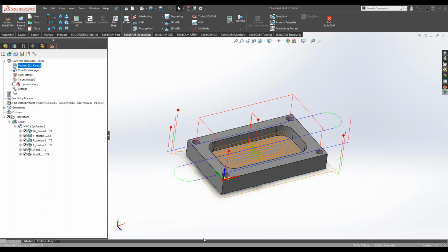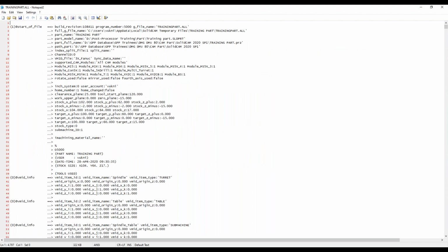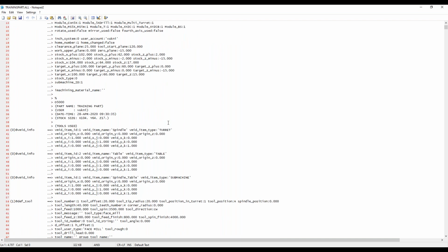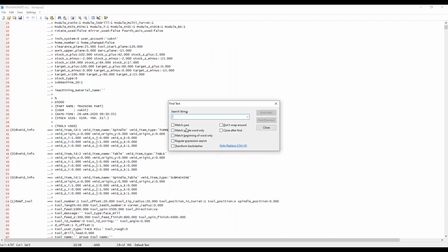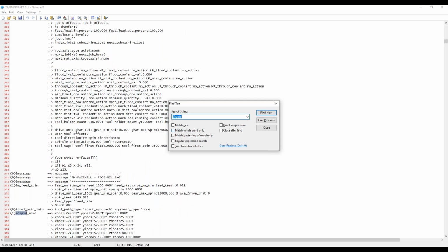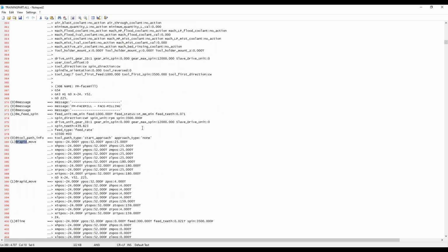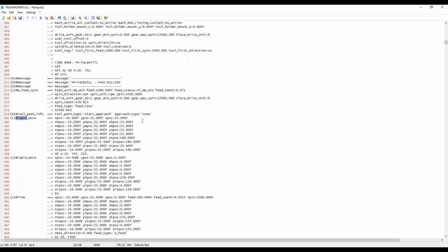Okay, let me move to the screen. Okay, now we have all of this data. Let's move to the, let's say, rapid line, or only, okay, rapid. Okay, so we have our coordinates. Now, the modality is used on many system variables, and you can know which one has a modality by searching the GPP help I showed yesterday, or by checking the trace 5 like I'm doing right now.